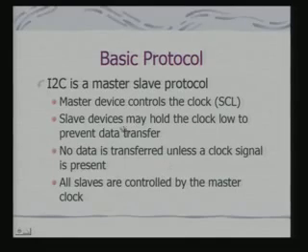So you can realize that using just two lines, by defining the circuit connection, a pretty sophisticated protocol can be done. Obviously, it is not as sophisticated in terms of protocol as your ASB and AHB, but still you have the features of multi-master control and arbitration, everything built using just two lines without involvement of an external arbiter. In fact, this is what we shall discuss in the next class.